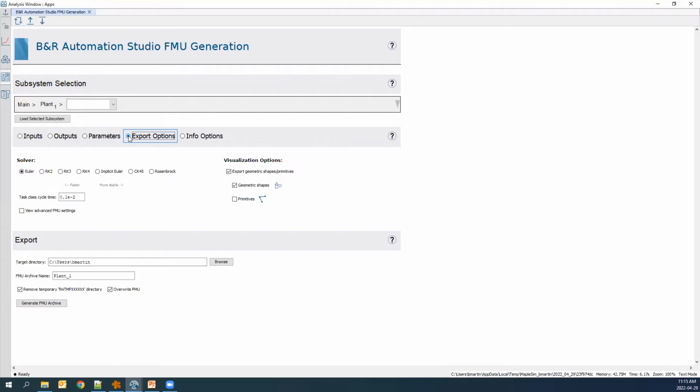This means you can bring the FMU to a computer or to a system that does not have MapleSim installed, and you can still run the FMU. This is different from other software companies, which will have different approaches. Some will embed it, some will not, meaning that you'll actually have to have the system with the software on it so that you can run the simulation, because it will communicate to it. However, having the solver embedded does make things a lot easier. It can really speed things up and keep you from running into more problems.